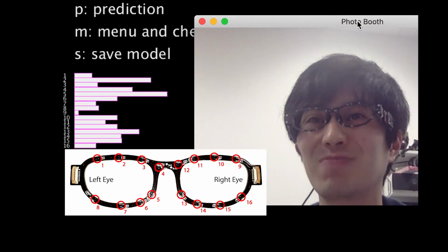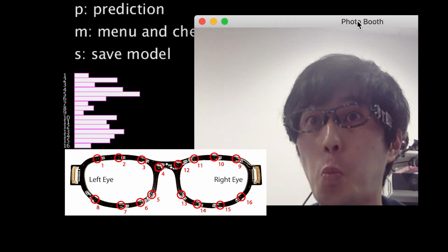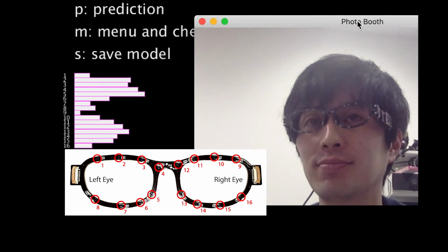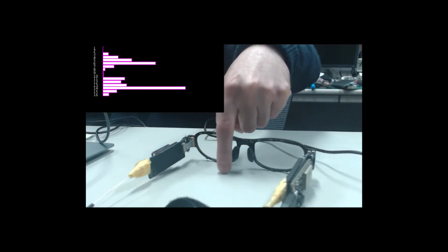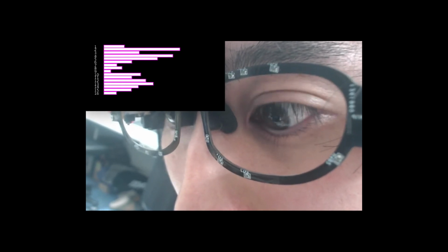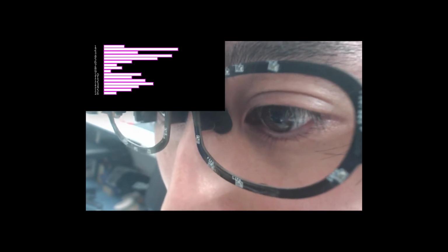We used 16 optical sensors which measure the skin deformation through reflective intensity. Depending on facial expression states, the sensor values change. Also, eye movement makes skin deformations, which change the sensor values as well. The sensor works like proximity sensors, and the eyeball movement changes the shape of the skin and the eyelids. This changes the distance between the sensors and the skin surface.